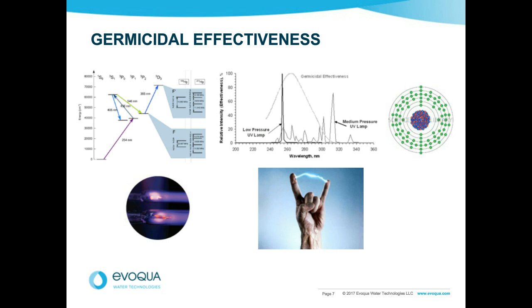All right. I think you touched on this topic a few minutes ago with another question, but is medium pressure more effective than low pressure for chlorine and chloramine destruction? It is. If we look at how chlorine goes in solution depending on the pH in different forms, each form does absorb UV more generally. So medium pressure tends to be a better way to dechlorinate. It certainly is a better way to dechloraminate.